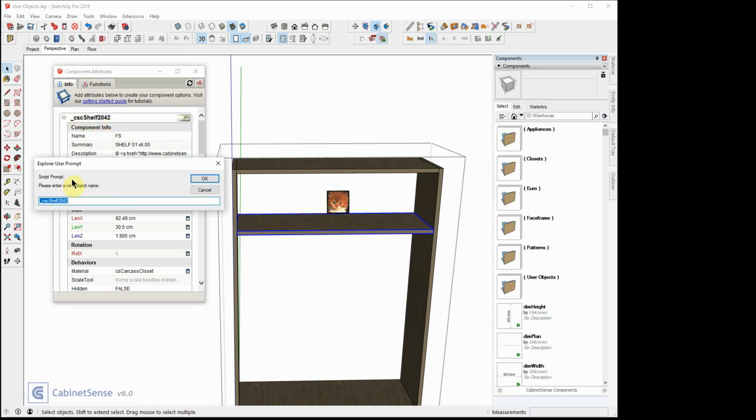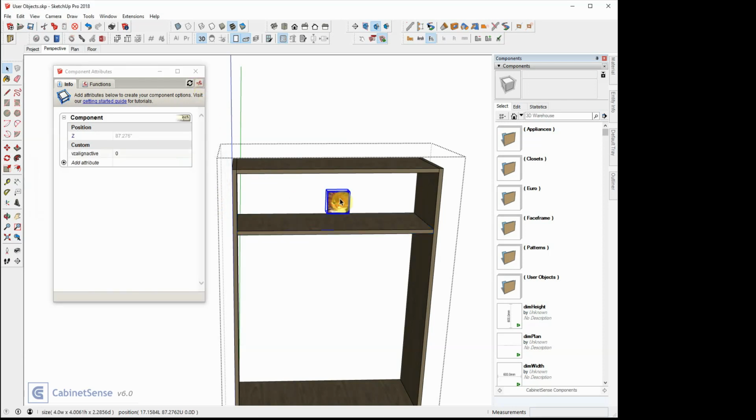So I'm going to double click, do a Control-C to copy the name, go back to my picture, double click to get inside, and you have to double click. That's telling the dynamic components you're about to enter a formula. Click equals to say this is a formula. I'll paste in the unique name of the shelf, exclamation mark, which then says the next thing that comes will be an attribute name, and it's simply Z. So I'm saying position the Z of this picture to be the same as the Z of the shelf.